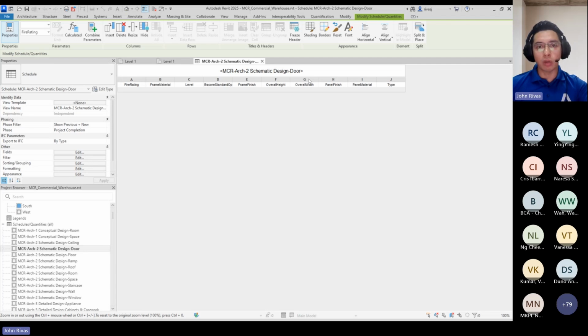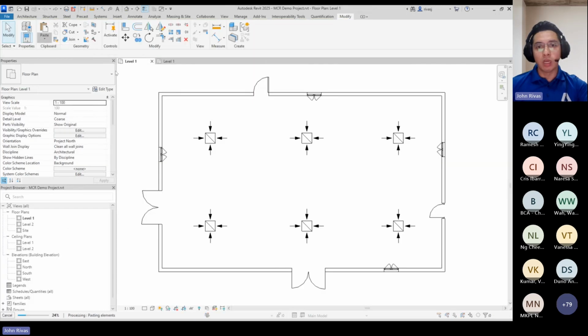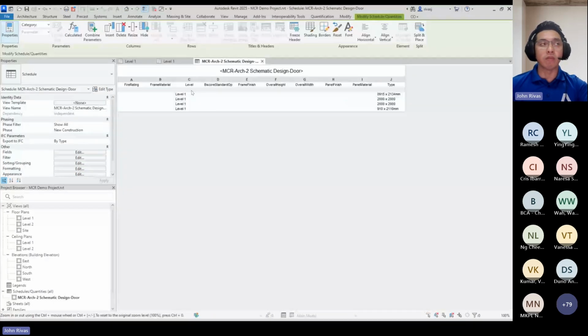And then when you go to my target project here, where there's no schedule that has been outlined yet, I can simply do a paste from clipboard. As I click that, it will automatically populate those parameters and schedules into the target Revit project. So going back, this is a manual approach and it's an easy configuration because you just need to get the target parameters from a source file.